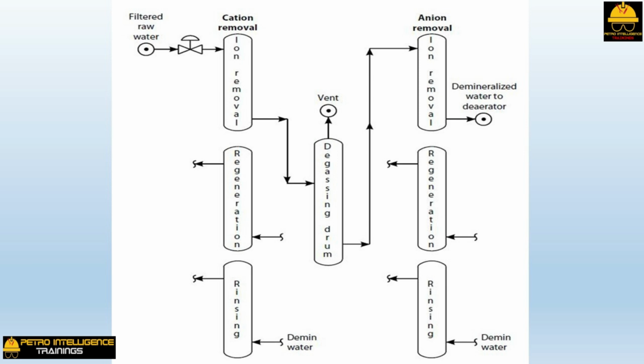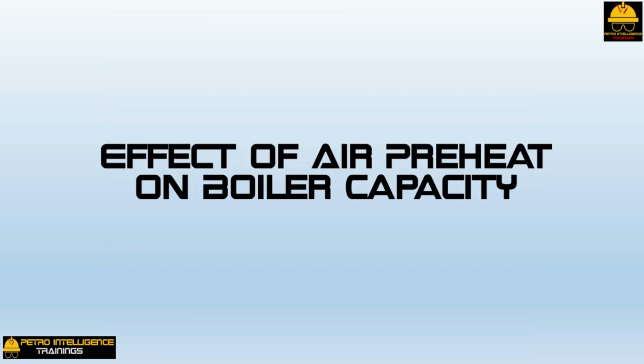Improper demineralization will also leave carbonates in the BFW. These carbonates will break down in the boiler to produce CO2. CO2 contaminates the steam supply to reboilers, where it is trapped. The CO2 accumulates and dissolves in the steam condensate to produce corrosive carbonic acid, resulting in tube failure in the reboiler tube bundle.